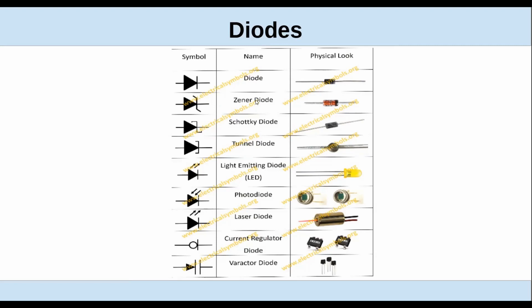And by the way they make the material, they could control that breakdown voltage, or the Zener effect. So they can do these at a whole range of voltages, 5, 10, 12, pretty much whatever you want, and use them as a simple voltage regulator with a resistor.